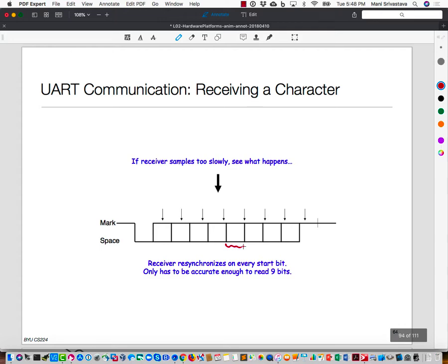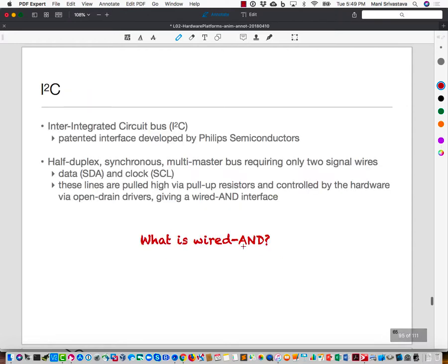You can also use the bit banging approach. If you have more UART devices to connect to than the ports on your MCU, then in a pinch you can fake a UART in software and just use some GPIO pins together with timers. So UART is very commonly used.